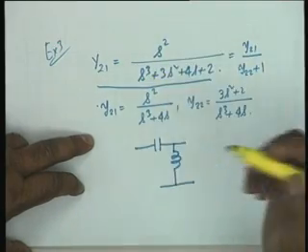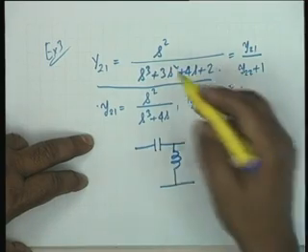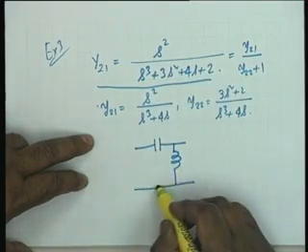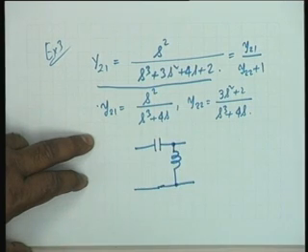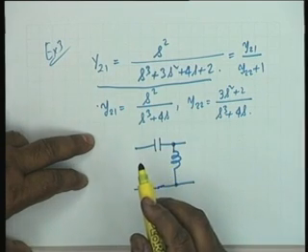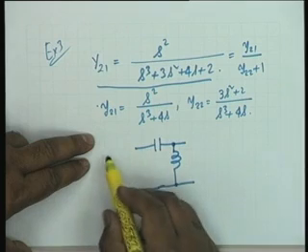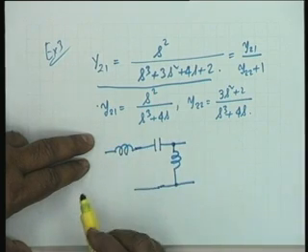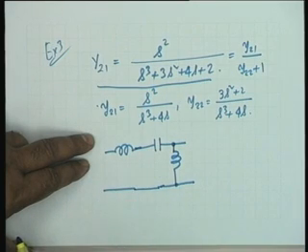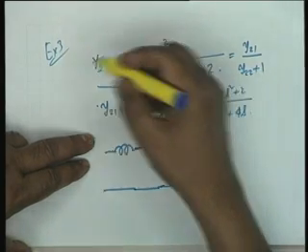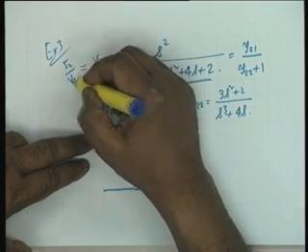infinity, s squared by s cubed, alright. And for 2 transmission zeros at the origin, we require an inductor in shunt and a capacitor in series. We also have a transmission zero at infinity, and to take care of that obviously we require an inductor in series. So we shall have indeed an inductor in series, okay. But now it is not a current source, it is a voltage source because it is Y21, Y21 is I2 by V1.